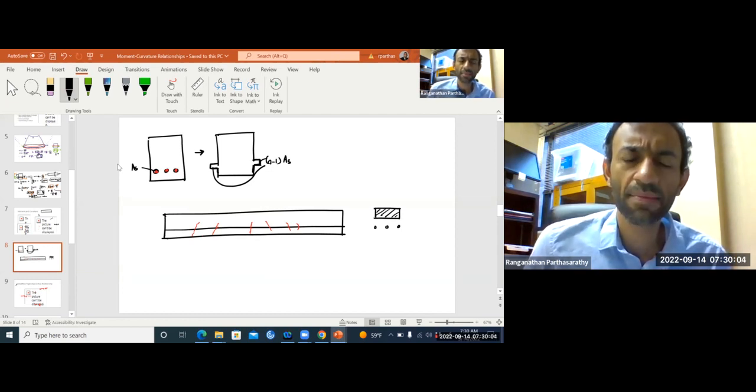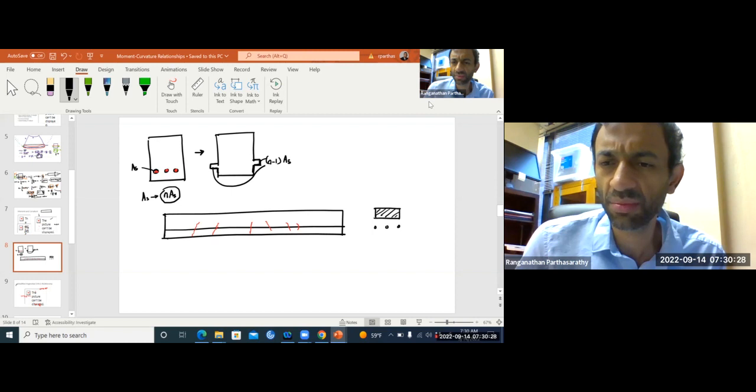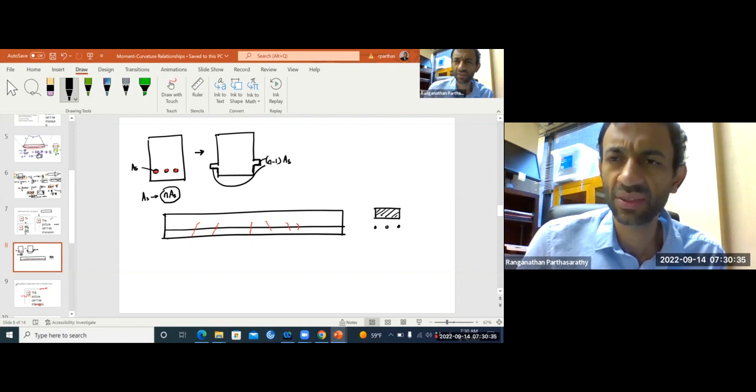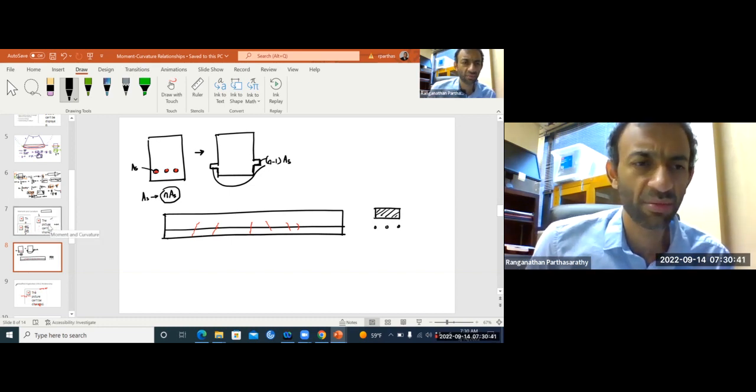Then you want to apply the classical beam theory. So you convert all this steel to equivalent concrete. So area of AS should be turned into N times area of AS. This is the equivalent area of concrete. So very briefly, do you all remember equivalent beam? Now, I didn't cover it in the recording. I was assuming that maybe you all remember, but maybe not.